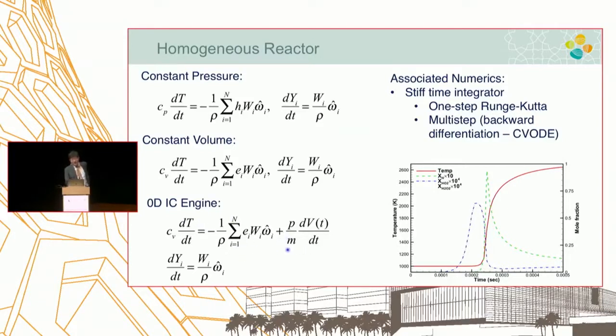But what it really is is still the same homogeneous box without valves, except the volume changes over time through the crank angle degree, prescribed as a function of time. There's crank angle data put into the system, and you can get a formula easily from the kinematics of the crank angle and connecting rod. You can find the volume as a function of time, integrate, and get the answer. This is the simplest and most commonly practiced computational model in the whole Chemkin suite.